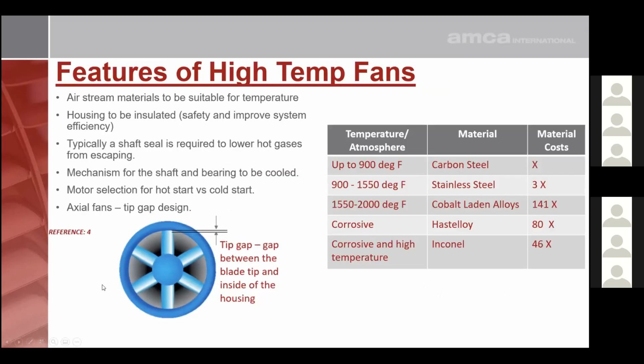Coming to the design of these fans, we first need to select the airstream materials that are suitable for the operating temperature. On the right side, you will see the materials. You'll notice that as you go above 1500 degrees Fahrenheit, the cost of the material substantially goes up. One of the things to note on axial fans is that the tip gap is very important in high temperature applications, because there will be expansion of the wheel, and if that gap is too small, the wheel will potentially hit the housing.